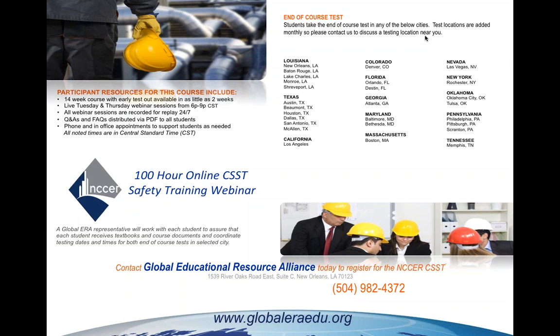Look at your 2 different pinch points, perfect examples on the left-hand side of page 7. It could be pinch points between the rigging and the load. It also could be pinch points between the hook and the rigging at the top, where they're not showing it, and then at the bottom, where an employee may not watch their hand placement when a load's being put down. You're not going to be able to physically manipulate that load, so watch where your hand and foot positioning is, and your body positioning.